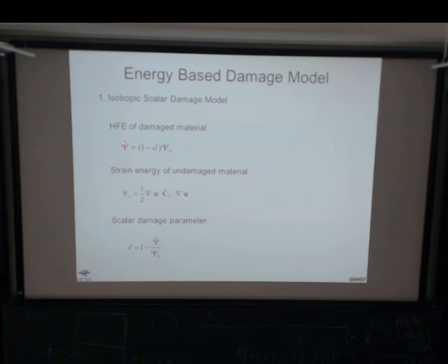So I have a complete history of that as a function of homogenized strain. And so from here, as you can see, you can easily extract the history of this divided by the undamaged free energy, and I'll get the evolution function for this damage parameter. Right? So this is through computation, and every different microstructure will give you a different curve. For large deformation? Yes, because it's a large rotation. So yeah, all those are taken care of.